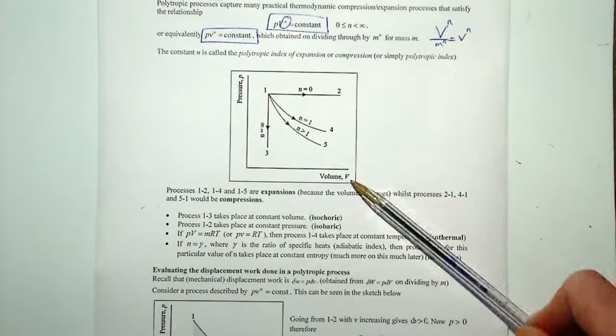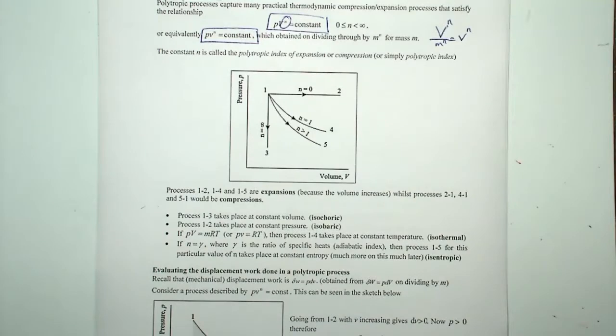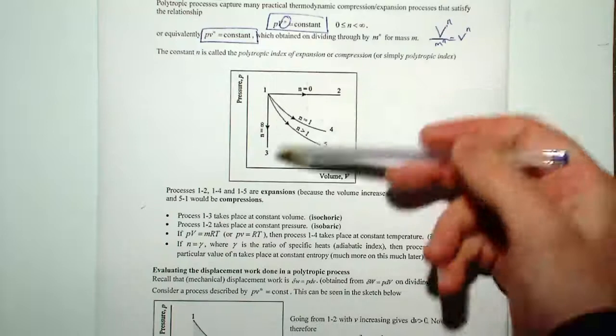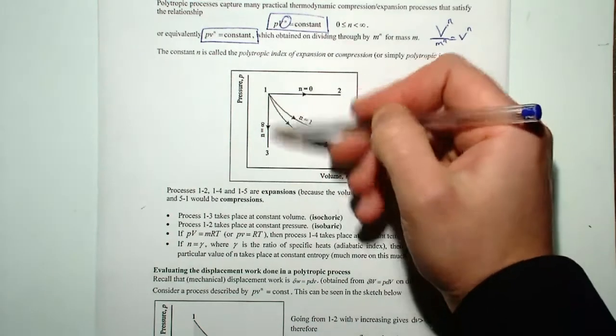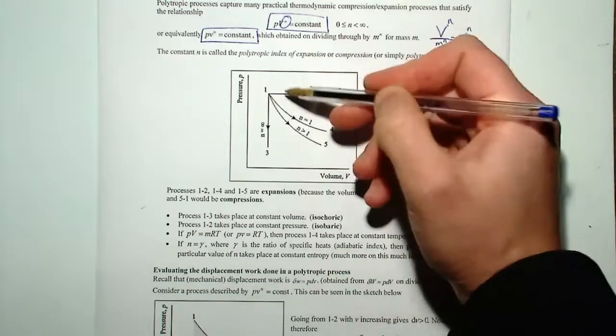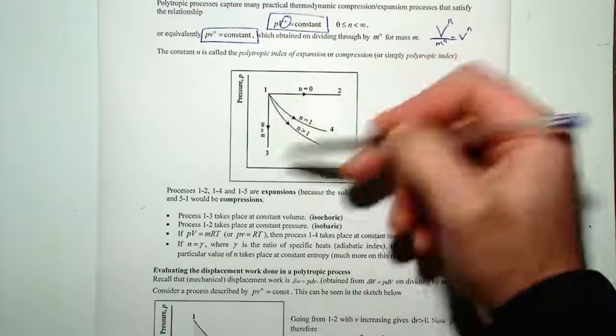So, mathematically, if you think about the value of n, this makes sense. Now we've got PV diagram. If you set n to 0, then, of course, you're going to have a constant pressure. So V is going to be 0, it's going to be 1, therefore you're going to have P equals a constant. If you have n to the power of infinity, then you're going to have a constant volume type of process. Essentially, pressure is going to change, the volume is not going to change. So you have this completely vertical line, which means the only difference is really in terms of pressure. Volume is going to stay constant.